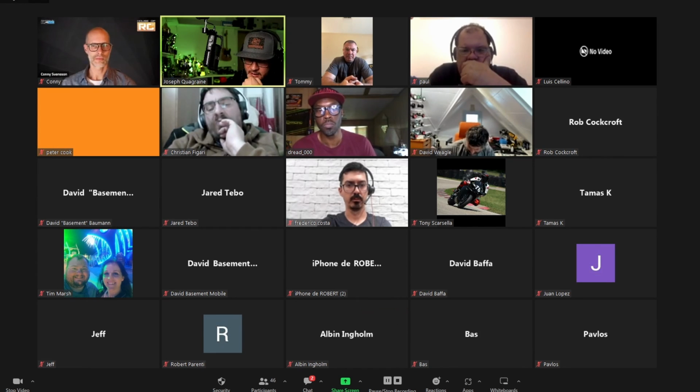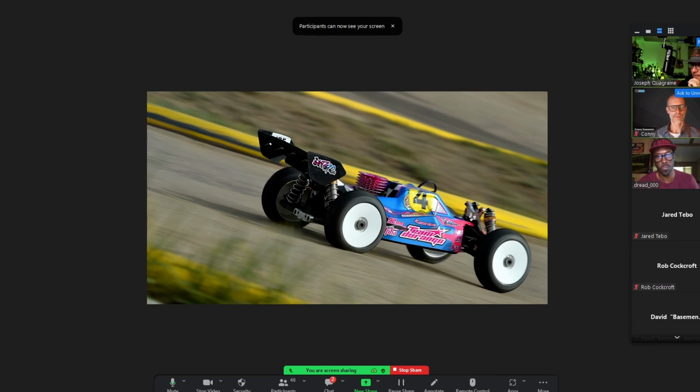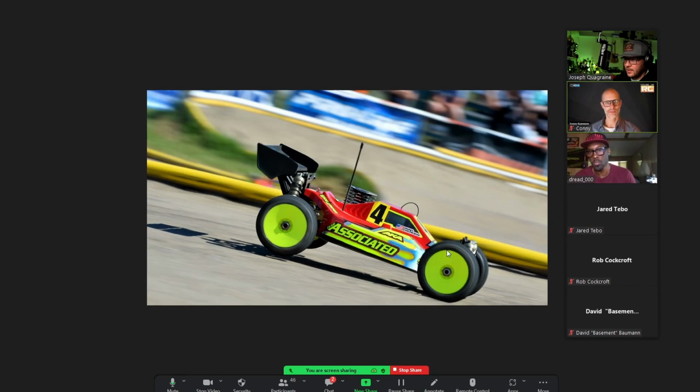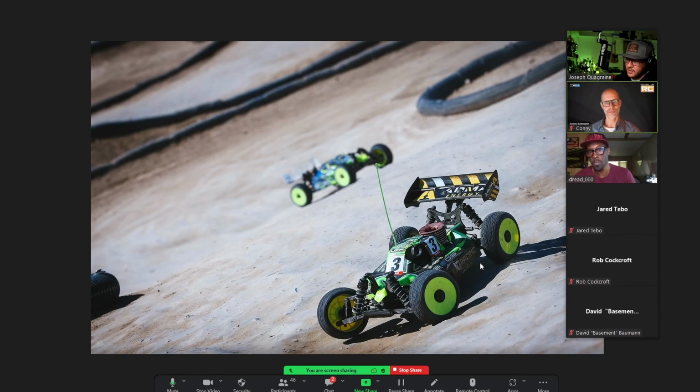So one thing that we need to make really clear is another myth in RC. We already saw these pictures before. We see a car here accelerating, the rear is squatting. Here, nose is diving. Here you see a car going around the corner. The car is rolling towards the outside. The fact that the chassis can move, that the chassis can roll and dive and squat, that's an indication that load is being transferred, but it's not the load transfer itself.